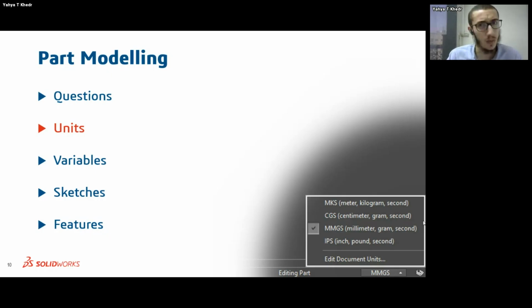So you'll have to go back again and then change your dimensions, or use the scale tool to scale the feature up or down. But that also means that your dimensions are not exactly how they should be in the design. So it's really a good practice to start slow, take your time to specify the units before you start doing anything, doing any sketches or anything.